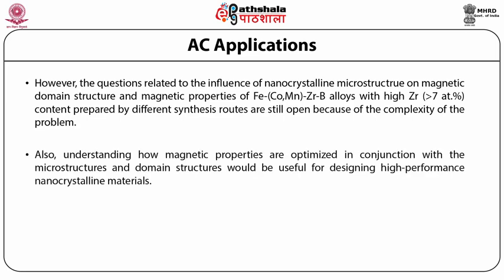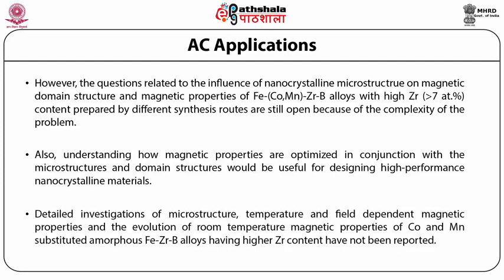Also, understanding how magnetic properties are optimized in conjunction with the microstructures and domain structures would be useful for designing high performance nanocrystalline materials. Detailed investigations of microstructure, temperature and field dependent magnetic properties and the evolution of room temperature magnetic properties of cobalt and manganese substituted amorphous iron zirconium boron alloys having high zirconium content have not been reported.